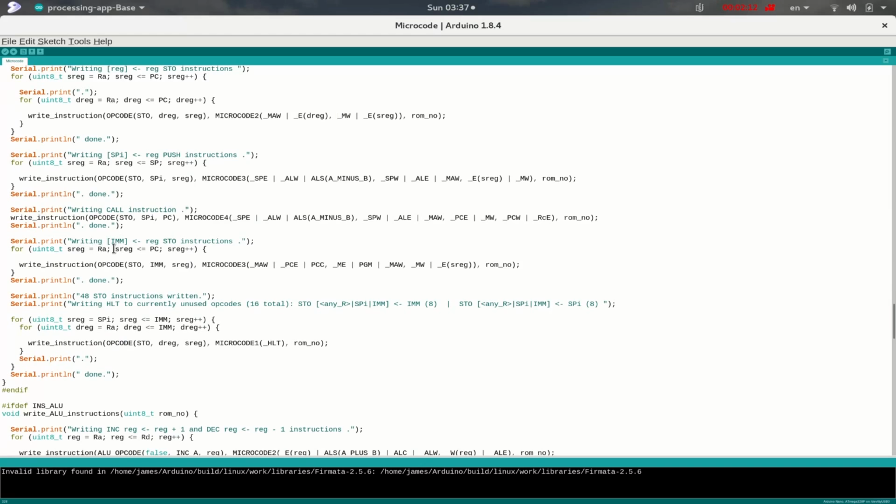But so again, for a store instruction, we can also have the address to which we want to store information in an immediate operand. And so we can do that using this kind of a store instruction. In this case, what we need to do first is to go and get that immediate address from program memory so that we can write it into the memory address register. So that the memory then is ready, pointing at data memory at this location, and we can actually write the value in this source register into that location.